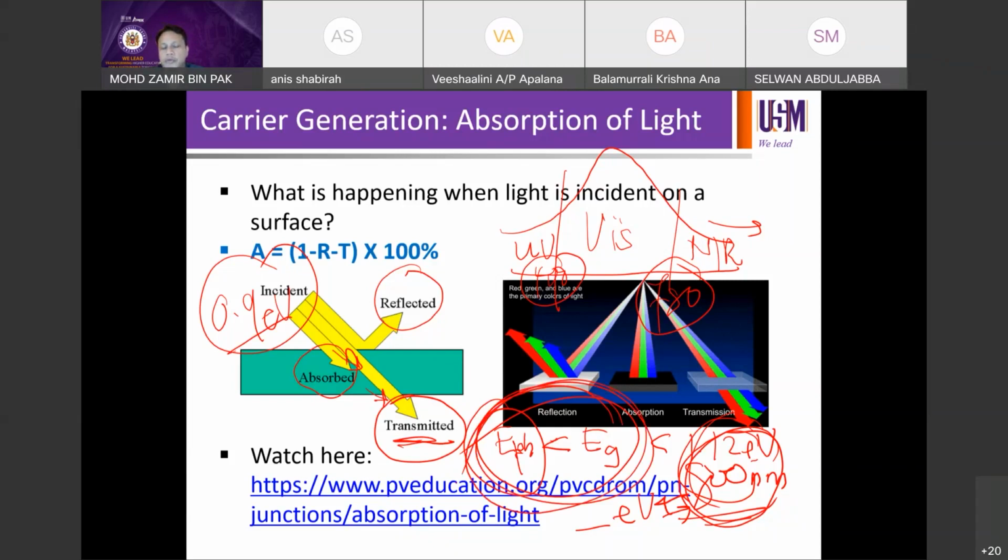If you want to work in the semiconductor or solar industry in particular, this is the thing, because it's all about light absorption and photon carrier generation. If you want to work in the solar cell industry in Malaysia, this is the thing. You have to be able to relate to whatever spectrum you have, what the wavelength and the energy are, and what is coming onto the silicon. Right, E equals hc over lambda: Planck constant times speed of light over wavelength, and the wavelength is this wavelength.